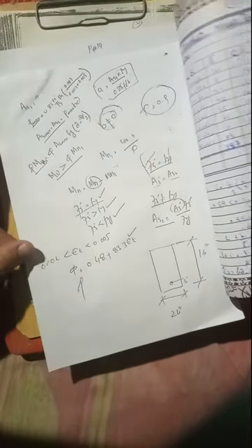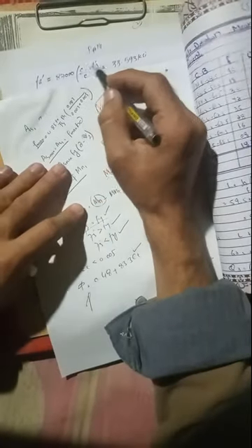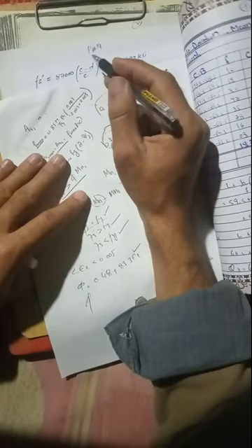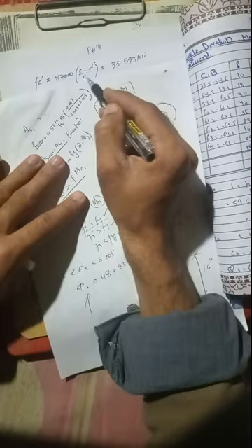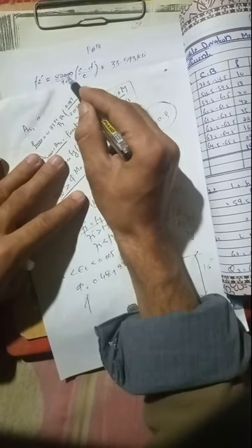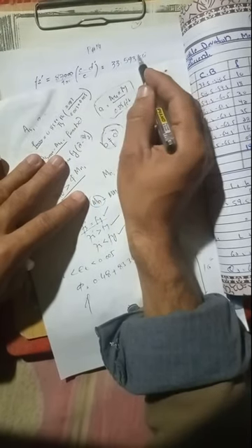Now use the equation of Fs prime, which is 0.85 Fc prime divided by Fy. Okay, so sorry, that equation is used for rho max. Now Fs prime, recalculate the value of Fs prime. Okay, so Fs prime equals 87,000 times (c minus d prime) divided by c. This is divided by 1000, because if you are using 87,000 then it will be in pounds. So divided by 1000, it will give you ksi, right?